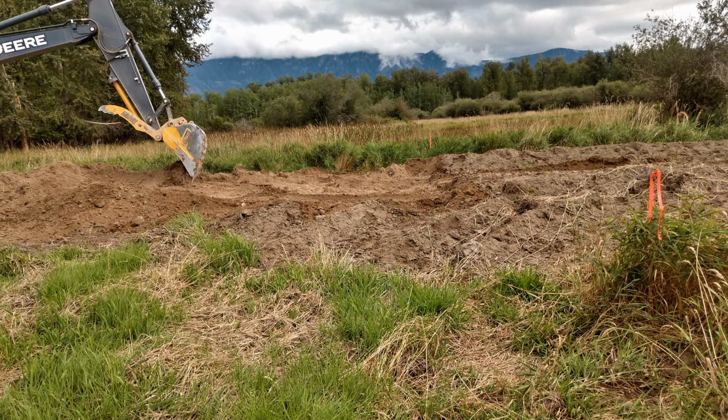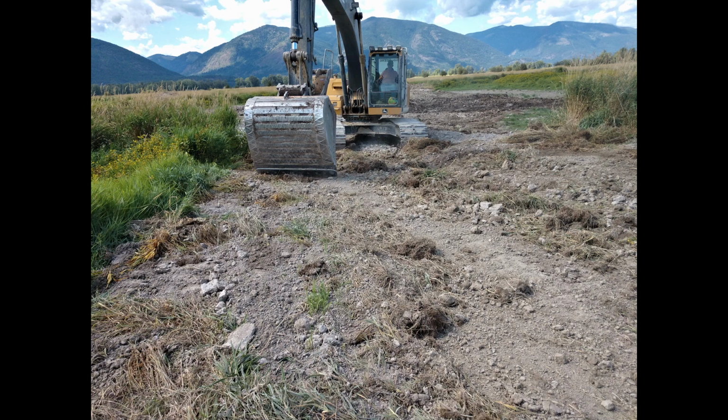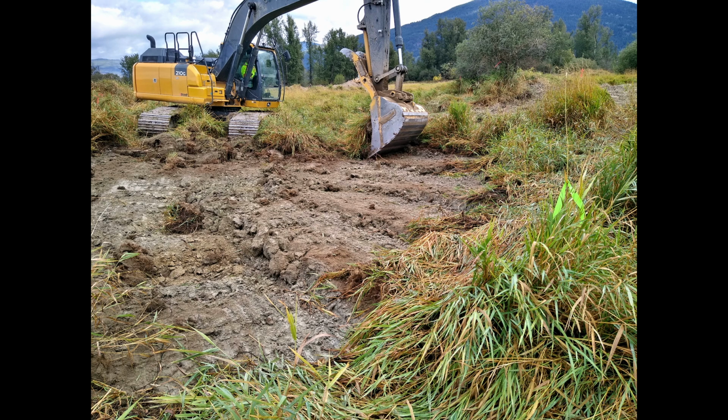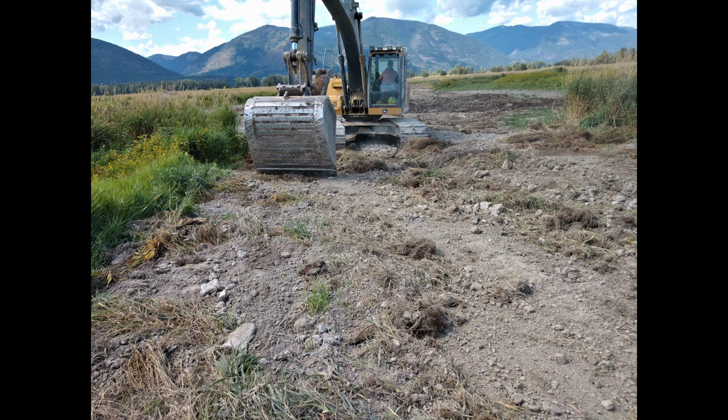The excavator operator begins the process of building a groundwater dam by removing vegetation and topsoil from the ditch to be filled. Plants and topsoil are removed from an area approximately 40 feet wide on either side of the ditch. Reed canary grass and its roots are removed from the area where the ditch will be filled. This topsoil and the reed canary grass will not be placed back in the restored wetland because we don't want it to grow. The next step involves building a groundwater dam at right angles to the ditch.